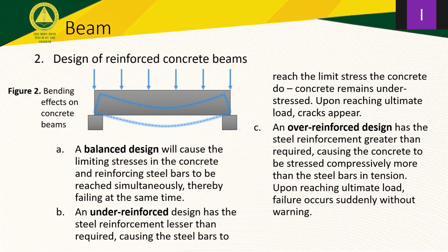The situation here is that we do not want to have an over reinforced design, because if that's the case, when the beam reaches the ultimate load, failure can happen without any warning. So it's either we go after the balanced design, but that is a critical value, which is just a little less than the over reinforced design.